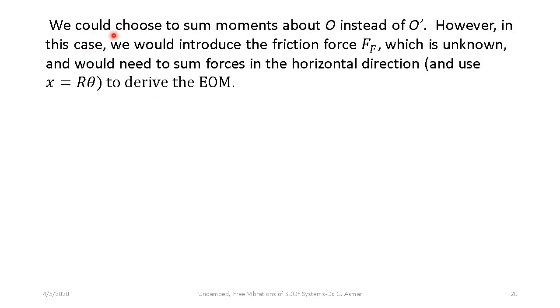Of course, we could choose to sum moments about O rather than O prime. However, in this case, we would introduce the friction force FF, which is unknown, and would therefore need to sum forces in the horizontal direction in order to obtain a second equation.